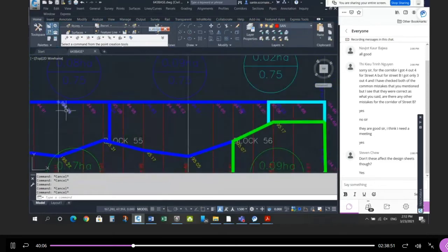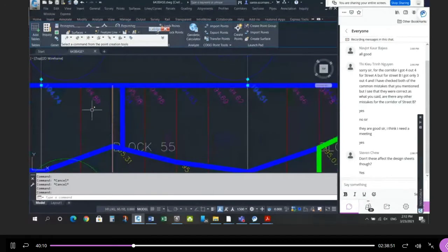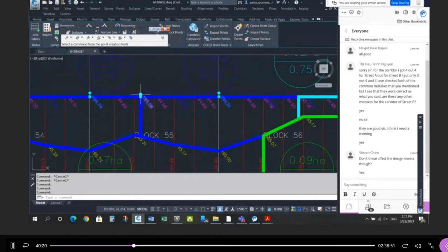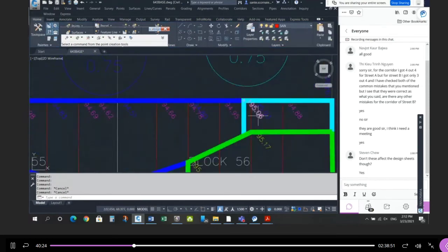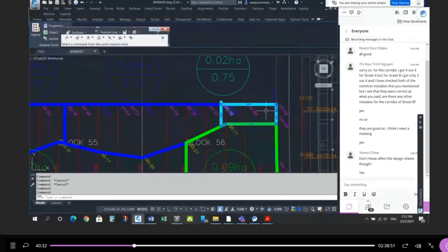Similarly here, right? So I know there's a catch basin here, 74. I know there's a catch basin here, 451. And if I do a visual inspection, 489, 504, 508, 498. So this is the high point, and that's why that division line is there. Okay, so that's the split point, and so on. So you kind of have to look at it. There's a division line right here, right? So this drains to the catch basin. This backyard drains to the road and into the street catch basin. So there's a little area here that goes into the existing road.